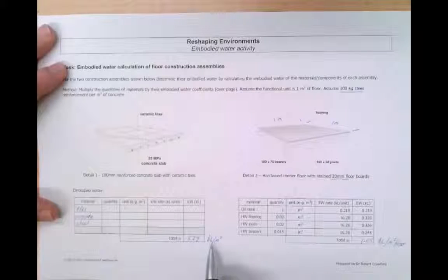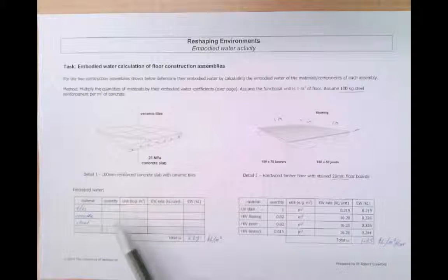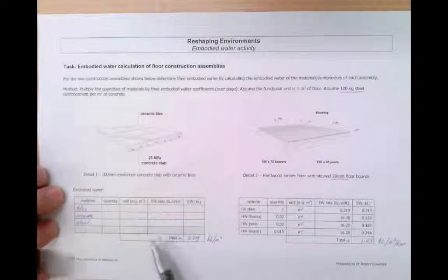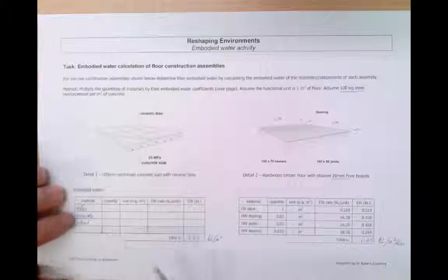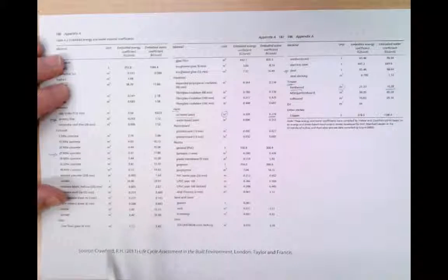And perhaps just one final point, a kilolitre is 1,000 litres. So we can see in this case that the embodied water of the concrete floor is about 3 times as much as the embodied water of the timber floor. So I'd encourage you to go through and do the calculations for the concrete slab, see if you come up with the same value, and then do the same calculation for the embodied energy. And for that, you're just using the same base data, but from the table, use the embodied energy coefficient, and you can compare the energy content of the two floors.